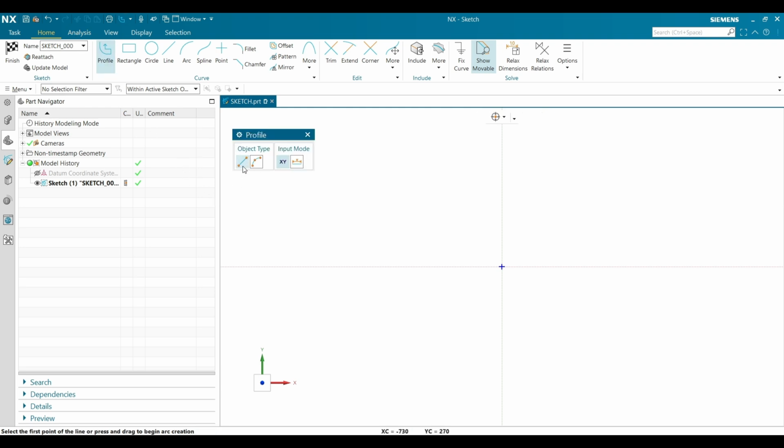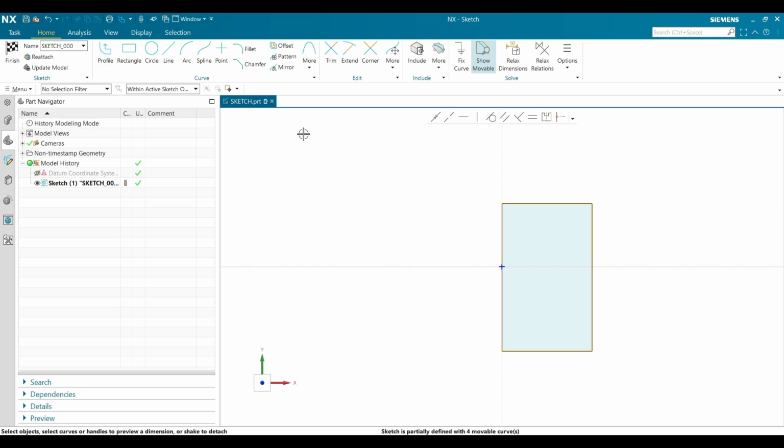At first we will start with line. Now first select the point from where you want to start the line, that is your first click. Now your second click will be the end point of the first line and starting point of second line. In continuous manner by 5 clicks create a closed figure. The blue shades suggest that the figure you create is a closed figure. Ctrl+A will select all the lines under Graphics window. Press Delete button to delete all lines.